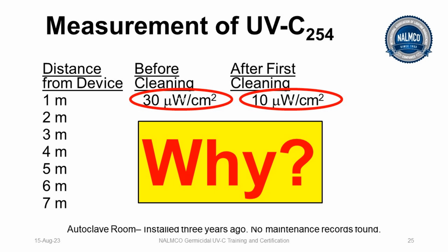But unless you have a meter and can show the workers why it's important to follow proper protocols, something like this will happen. The person was actually just using a detergent in water with a cotton rag. So when she was cleaning that lamp, what was happening? She was putting a surfactant or a coating on the UVC lamp. She was spreading out whatever settled on top onto the entire lamp. And the bottom line was that the UV went down.